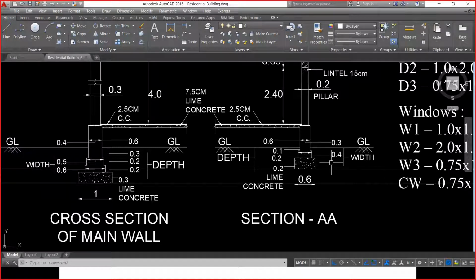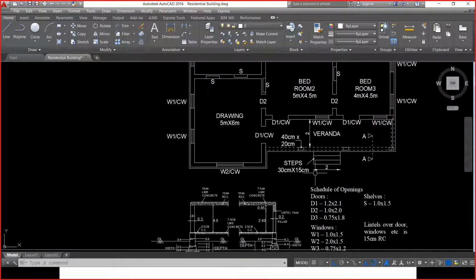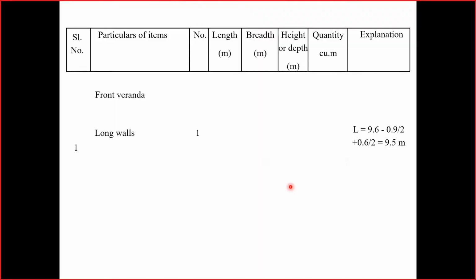by the crude method or the thumb rule, as I have told earlier, to go on with the length calculation. For the long wall calculation, center to center distance plus width of the item will give us the total length, but only in specific cases. It is not in general. In general, it cannot be applicable. Why it is happening is because we are basically doing the deductions for the things which is already being constructed.